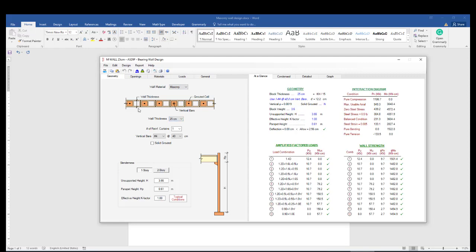The masonry wall looks like this, the same as we discussed previously, and this is one block which has two holes. There is an option to grout one or both. If using solid grouted, then all cells will be grouted, and the material weight is calculated accordingly. So it's better to leave them empty, or use some sort of lightweight material that can reduce the weight on the foundation.